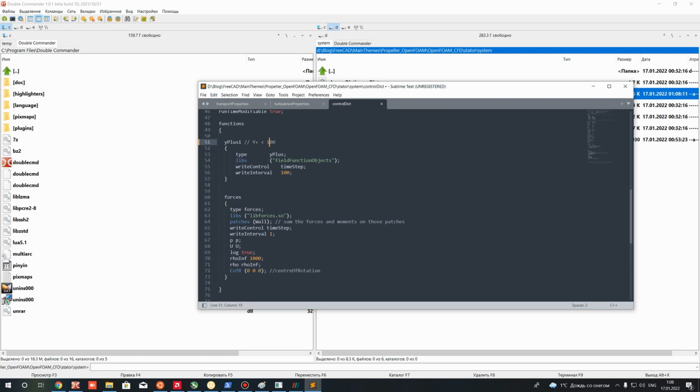But if you are working in science and you want to validate the simulation or for another purpose, your criteria for y plus will be less than 5, maybe 1, for cases with the Omega SST turbulence model.